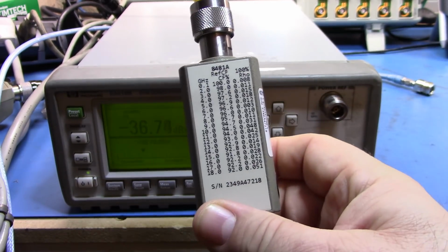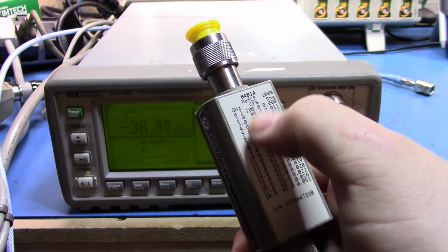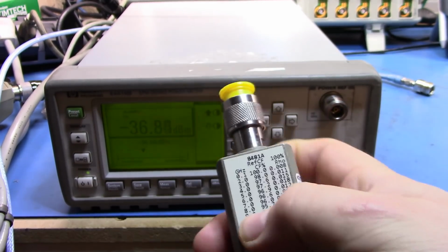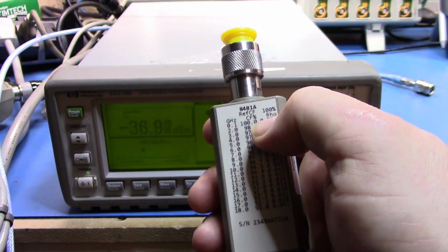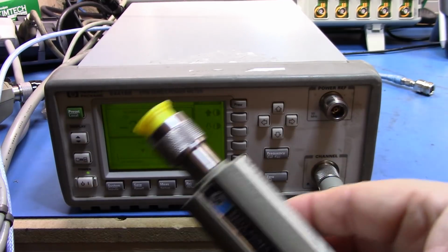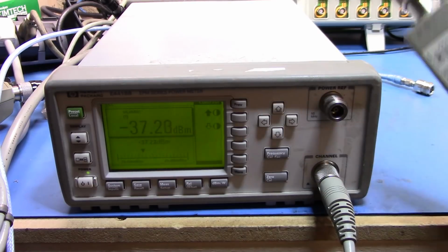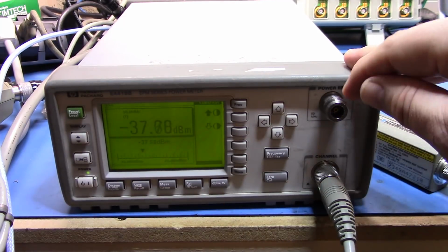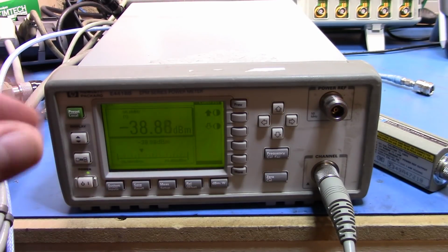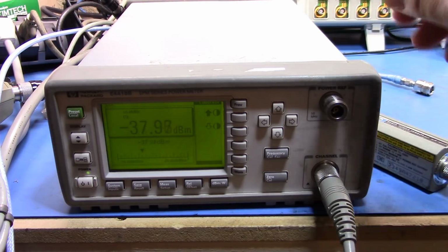And this is an 8481A power sensor that goes from 100 megahertz to, or actually from about 10 megahertz up to 18 gigahertz. And you can see that I have the power factors here. Now this has been off to Keysight and has been calibrated, so it should be reasonably accurate, given that these things are an open loop power meter. So unlike the 432s or the crystal detectors, which give you an absolute value of the power they're actually measuring, these work on the accuracy of the underlying power reference here.